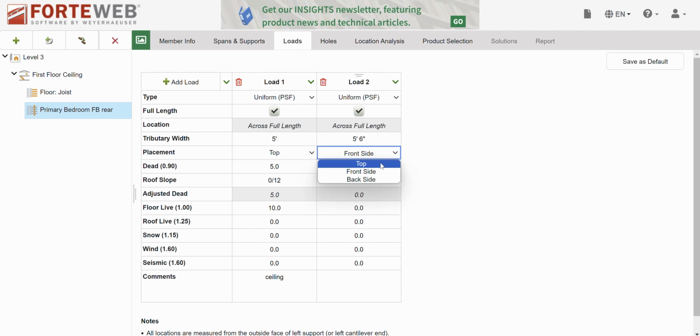5.5 feet on top. Dead load of roof is 10 and 20. Okay, and there's a roof slope. We're going to check the plans for the roof slope. And it was a 10-12 here and a 3-12 here. We're not concerned with the difference in the 3-12. We're just going to say 10-12 and be conservative. A little bit extra weight, no big deal. All right, so we'll go to a 10-12 roof pitch. See how that raises the dead load effective? This is the roof. All right, great.